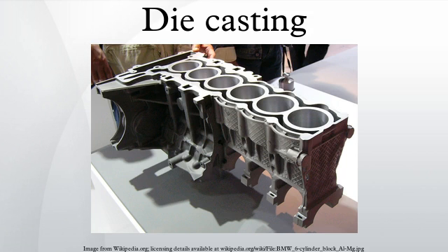Depending on the type of metal being cast, a hot or cold chamber machine is used. The casting equipment and the metal dies represent large capital costs, and this tends to limit the process to high-volume production. Manufacture of parts using die casting is relatively simple, involving only 4 main steps, which keeps the incremental cost per item low. It is especially suited for a large quantity of small to medium-sized castings, which is why die casting produces more castings than any other casting process.